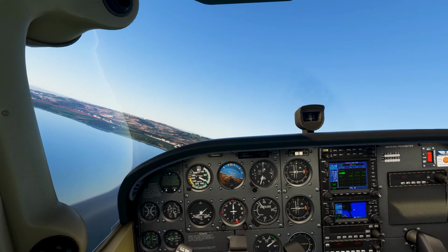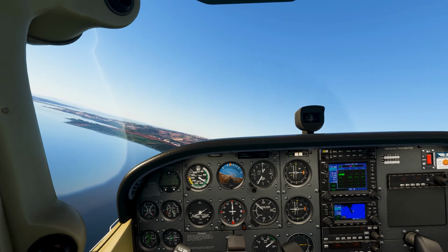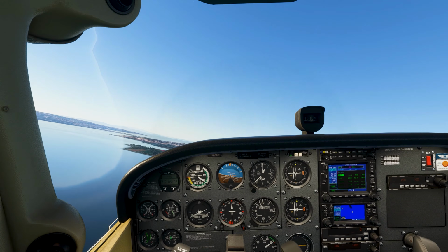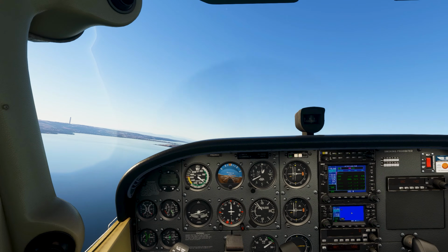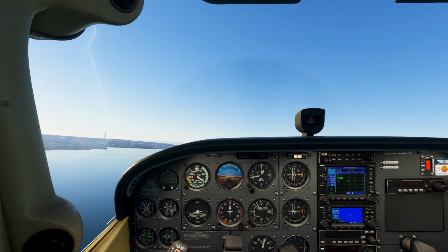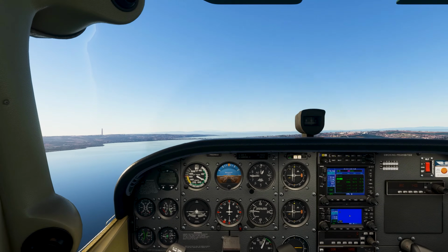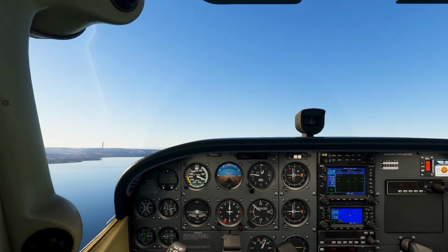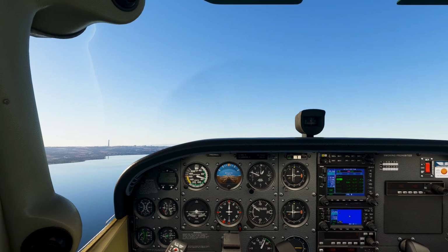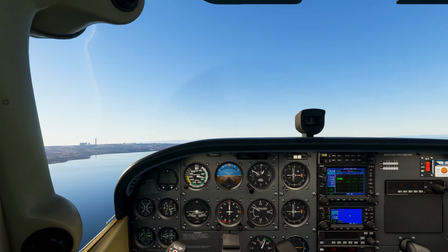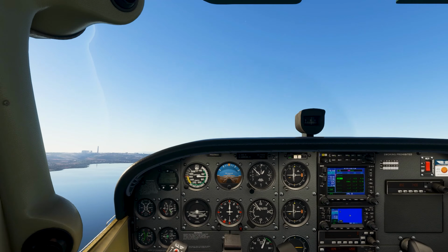A transponder mode refers to the different ways an aircraft's transponder can communicate with ATC and other aircraft. For example, imagine an ATC station on the ground and an aircraft in the air. The ATC station sends a request for information from the aircraft. The aircraft's transponder then replies to this interrogation. The transponder mode determines the format of this reply.